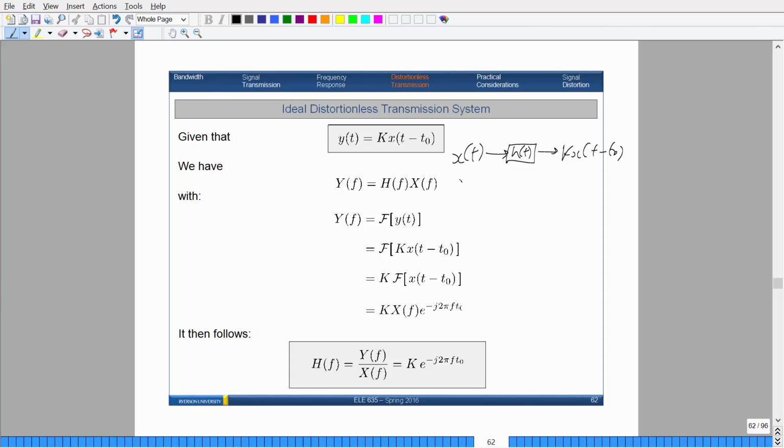So if I decide to take a look at this in terms of the frequency domain, remember, what's going to happen is that I need to perform multiplication. So I have to multiply these two things in order to get what the response looks like. Or you want to convolve this in time domain. So this is in time here, and this guy here is in frequency. Okay, so that's what we want to take a look at. So you just multiply the two together, that's fine.